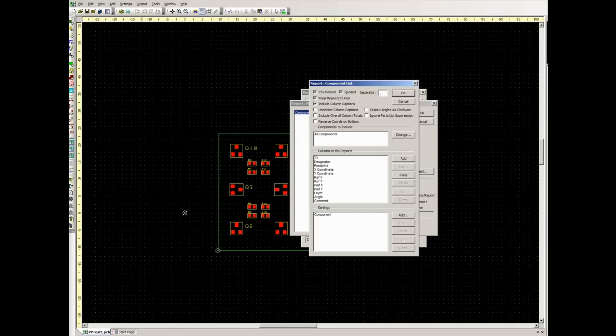Designator, which is the name, and comment, which is also the name, and these are used to allow the software to extract information it needs on the feeders that are required. The X coordinate, the Y coordinate, and in some CAD systems you'll have a ref X, ref Y, pad X, pad Y, and these are just information about the pads. As I said, the software can work out the size of the component, but we don't use this, so they will be set to 0.